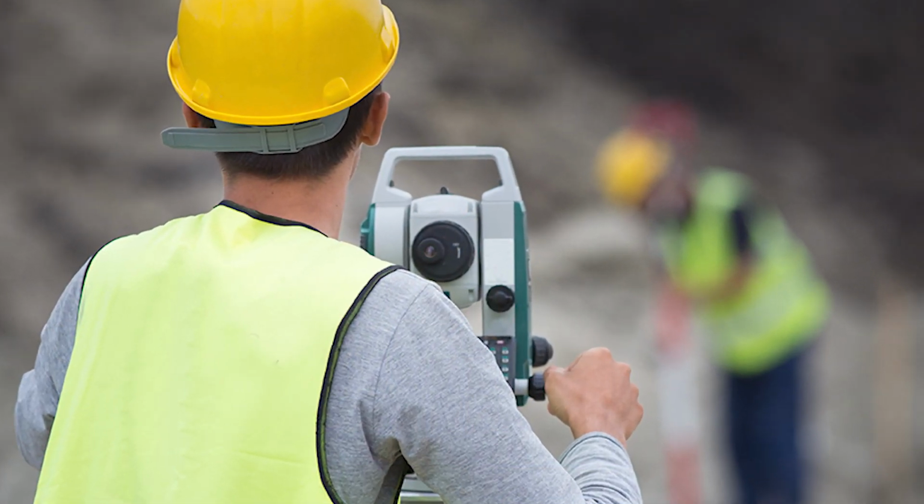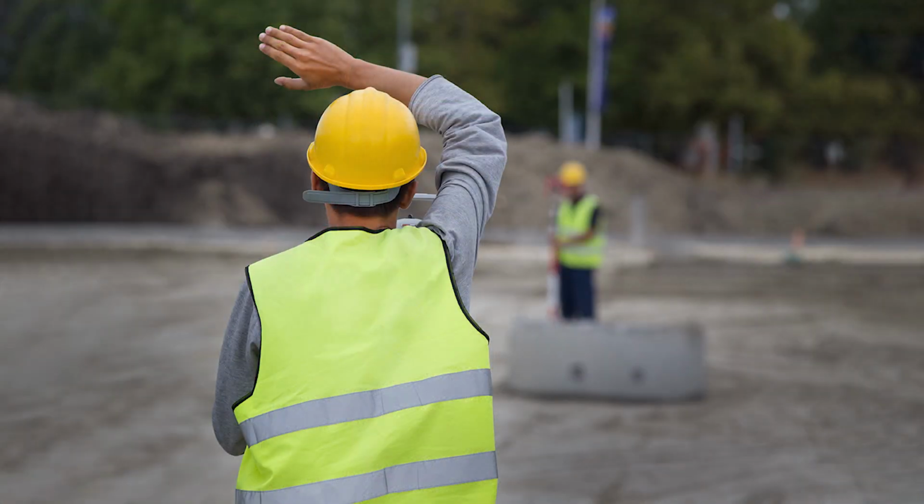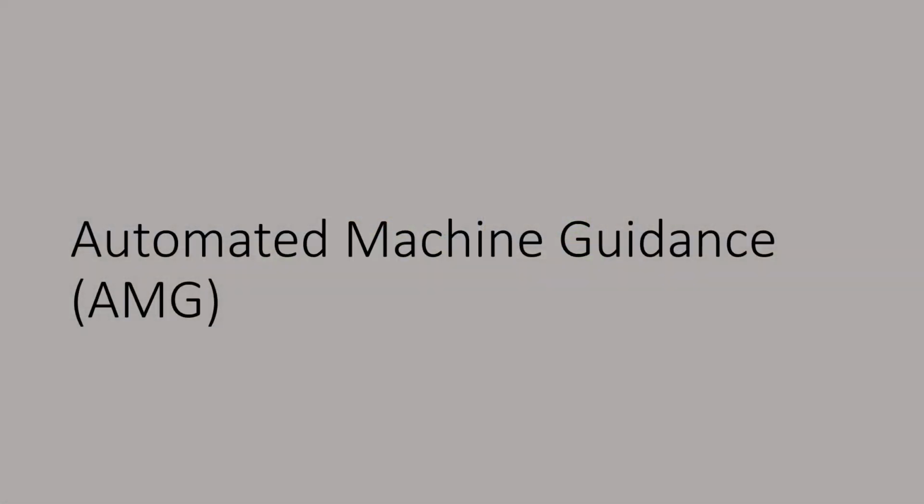You cut too much, or you didn't cut enough. Make another pass, survey it again, another pass, or finally dial it in. We'll show you some screenshots in a bit on the machine guidance where you'll actually have the model right there, and you can see the blade is where you want to be as you're going through.